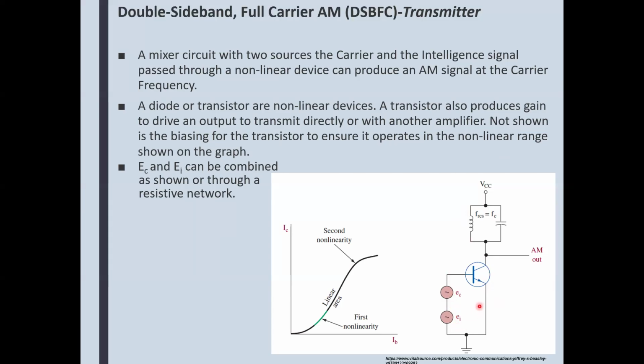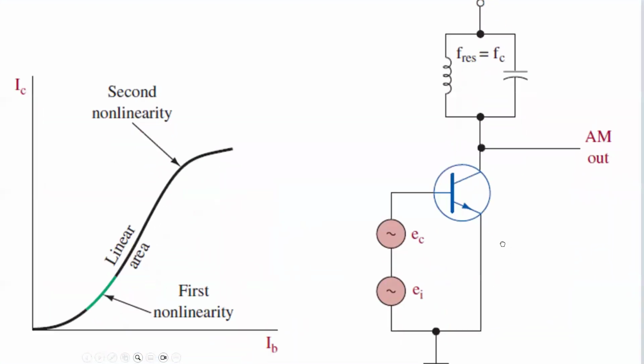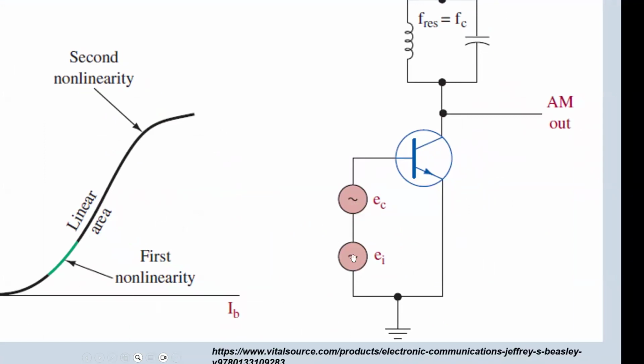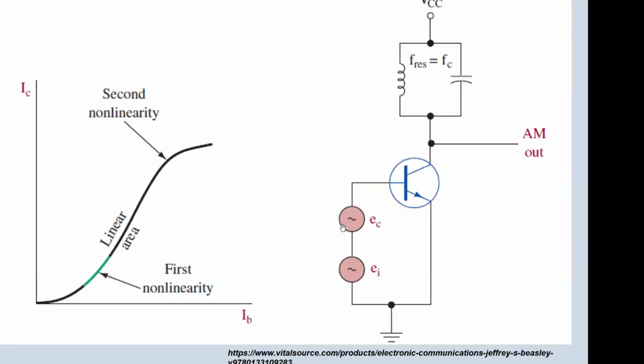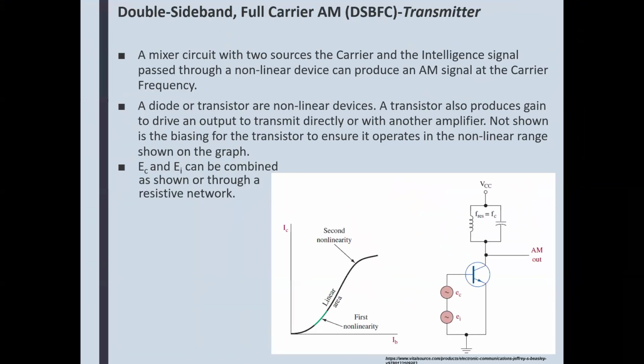Now we can also do this. We could connect those two sources, except we have to make sure that the grounds are not going to create any conflict. So we can connect those two sources in series and just adjust the levels on one and the other, and that's the simplest way of doing things. So if you see something like that, or if you see that thing with the wiper, that's fine.